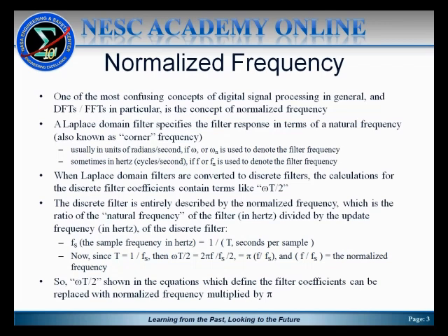As stated, one of the first things we'll talk about today to set the framework again for some of the concepts that are somewhat confusing about discrete or digital filters is normalized frequency. What do we mean by it? You may recall in earlier parts of this discussion, normalized frequency is the actual frequency divided by the sample frequency, and it typically runs, for real discrete sequences, from 0 to 0.5, where 0.5 represents the Nyquist frequency, as it's called, which is half the sample frequency.